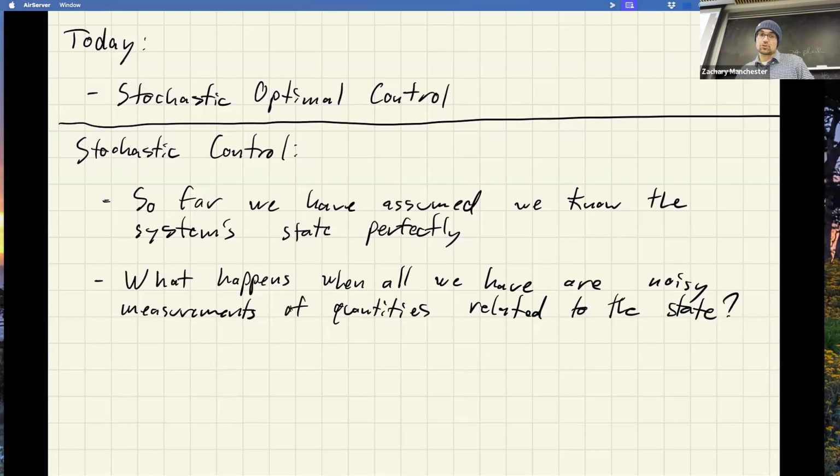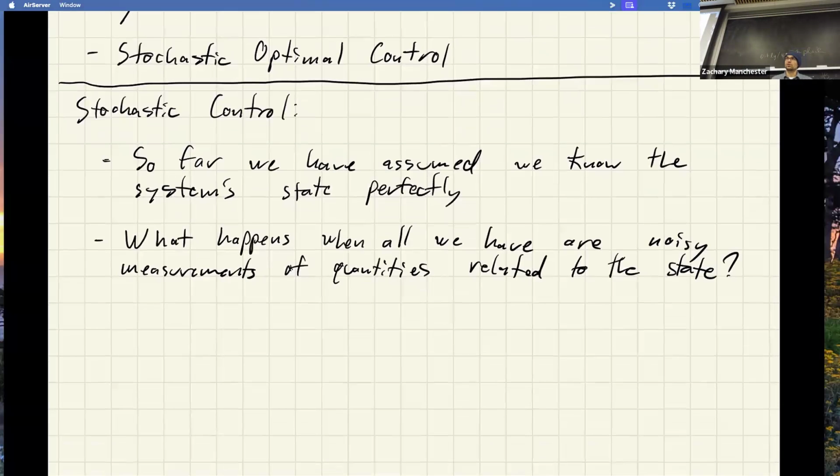And so, this is really always the case, even in contexts in which you have pretty good measurements, like say if you're in a motion capture arena. Those things are pretty good. You can get sub-centimeter accuracy measurements on these markers, right? And they'll give you the full rigid body pose. But even in that context, those things will just give you the pose. They won't give you the velocities. You can figure that out a bunch of ways, but even there, it's a little subtle, right? Those things do have error. And if you were to naively finite difference the stuff coming out of that thing to get the velocity, well, finite differencing introduces noise amplification and all kinds of potential badness. So even there, it's not a great idea.